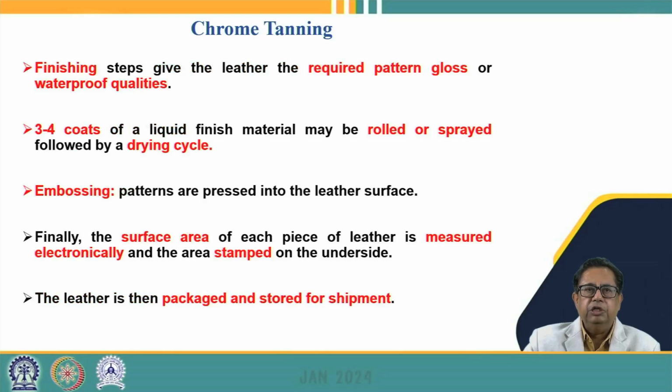So the finishing processes may also be used here. For example, we can provide a further gloss to the leather that is produced. This may enhance the waterproof qualities of the leather. Here we use liquid finish materials which we roll on or spray on. For example, we can apply 3 to 4 coats of those finishing liquids, followed by the drying cycles.